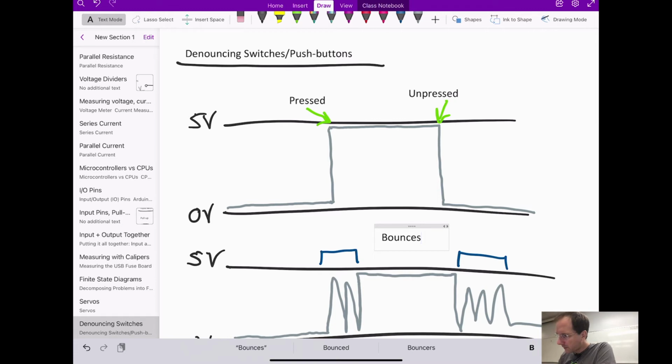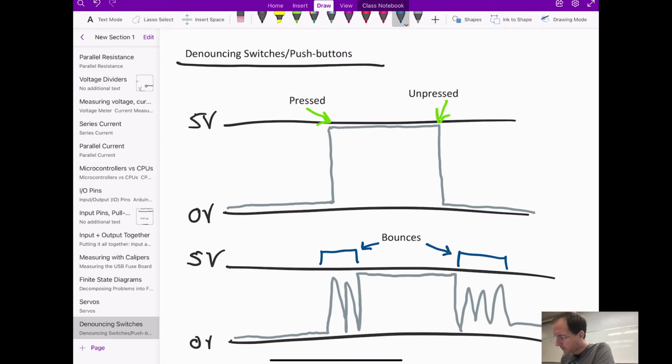And bouncing is not good for a variety of different reasons, which is to say that it becomes a challenge that you have to deal with in software. Because if we consider that there's some magic threshold, say 4 volts and 1 volt or what have you, that the system counts something as either being a 0 or a 1, then we clearly exceed that threshold some of the time and then go back down and are now counted as a 0.